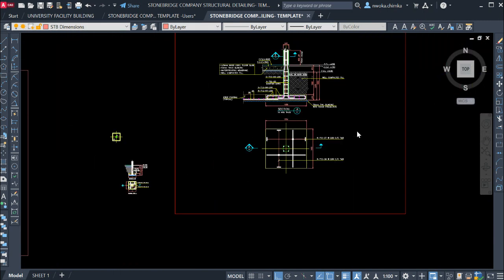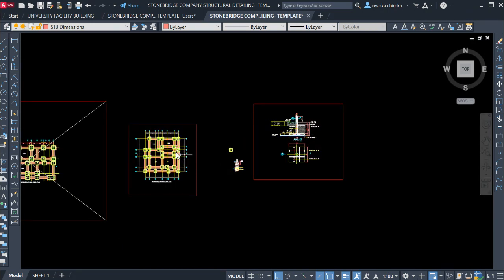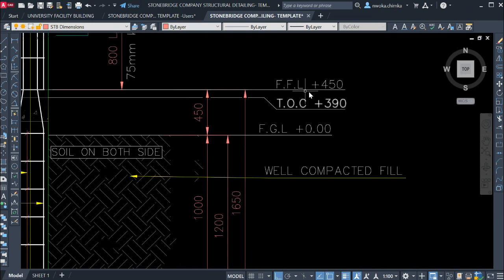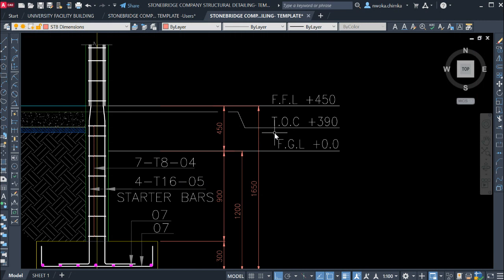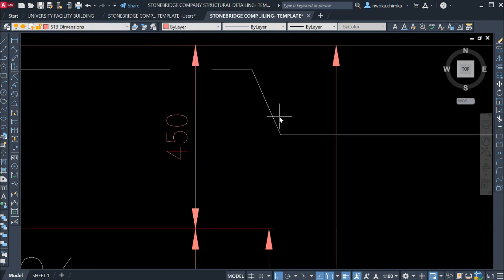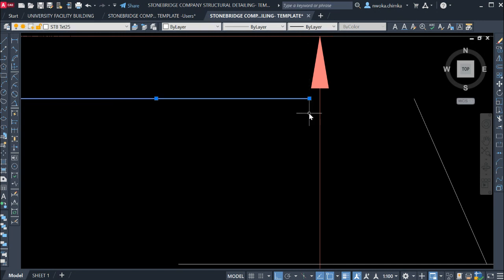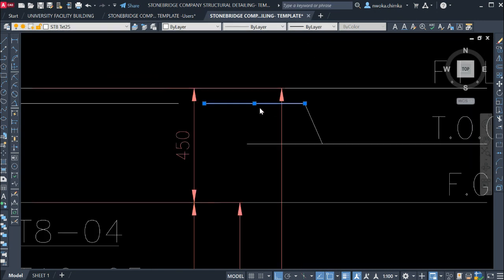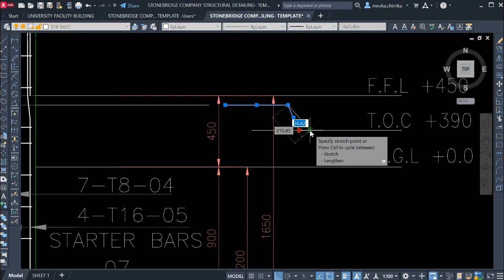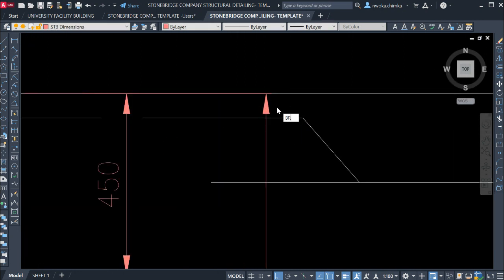If you check how the dimension of this one is, you can see how it looks. So we now stretch all these line points to match the same thing, and then do this, and then move this one forward and keep this here. Then try to move a line up to this point and keep this here, or move to join it with the line first, and then shift this to this first, and then use BR, break, to break off this point from this point.